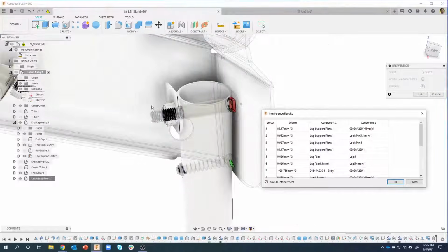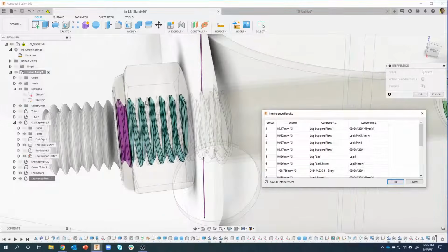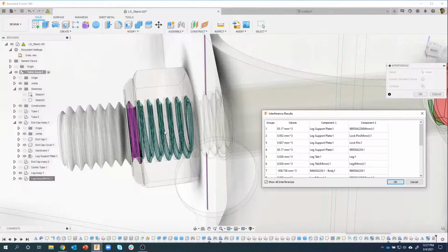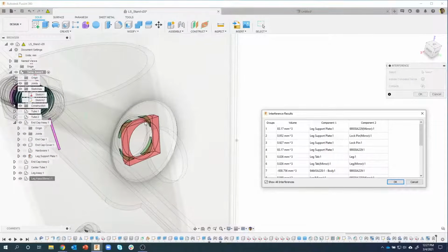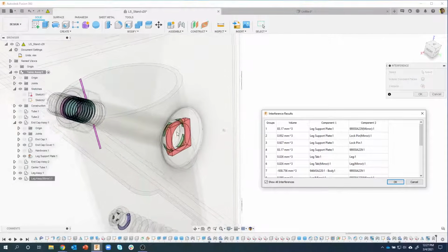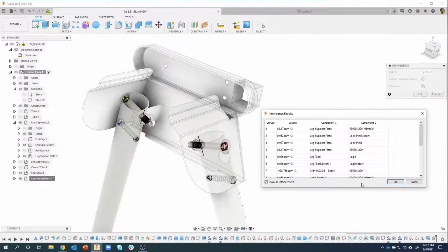And I do that. In fact, with threads, you can pretty much ignore it, because it's really tough to get it right. I could rotate the nut so it's actually binding with the threads the correct way and all that kind of stuff. But this is exactly why I think people are asking the question: I have a round hole and we're putting a larger square head through that. You guys are kind of thinking ahead. I think you know me now. This is, I'll be honest, how I design. I'm like, okay, I'm assembling this thing together. It's looking great. I will run a clash analysis or an interference analysis after a while and see what's clashing.